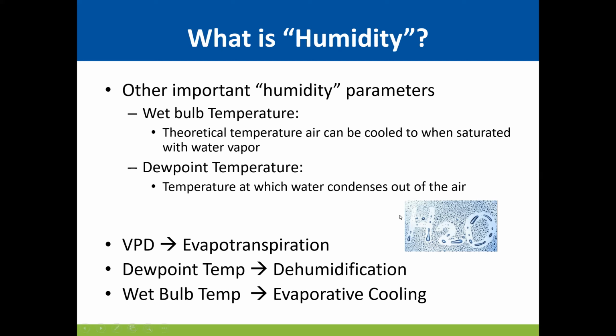So those of you who have greenhouses, say in Ohio or another cold climate, when it's really cold outside, the surface of your greenhouse cover gets cold. But you're holding a condition of, say, 80 degrees and 70% relative humidity inside, and that water now condenses on the cold cover, and that's why you get dew forming on the cover of your greenhouse.